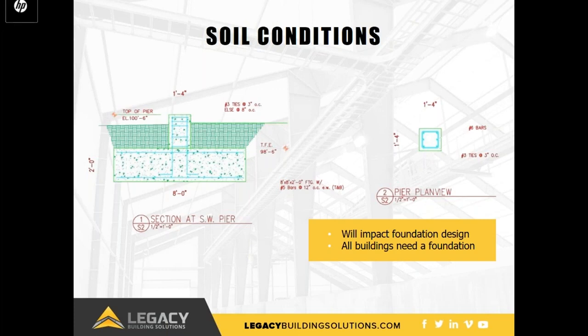Fabric buildings are comparable to pre-engineered metal buildings, and they have nearly identical foundation requirements. If a fabric building manufacturer is claiming that a permanent or semi-permanent building does not require a foundation, ask them to back that up with accepted engineering calculations.